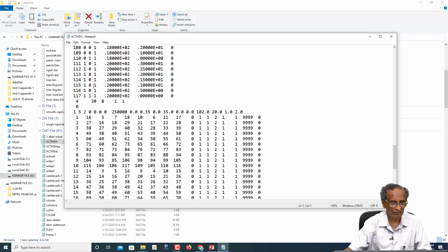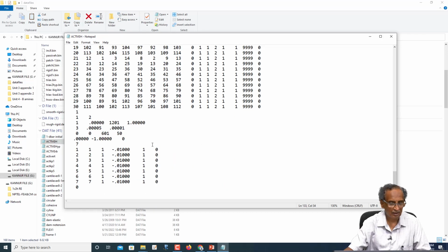And here, when you give the material point data, the last value that you give is the K naught. So, this is the K naught of 2, okay, and then we are going to demonstrate the active pressure case, and let me just run this for one case.